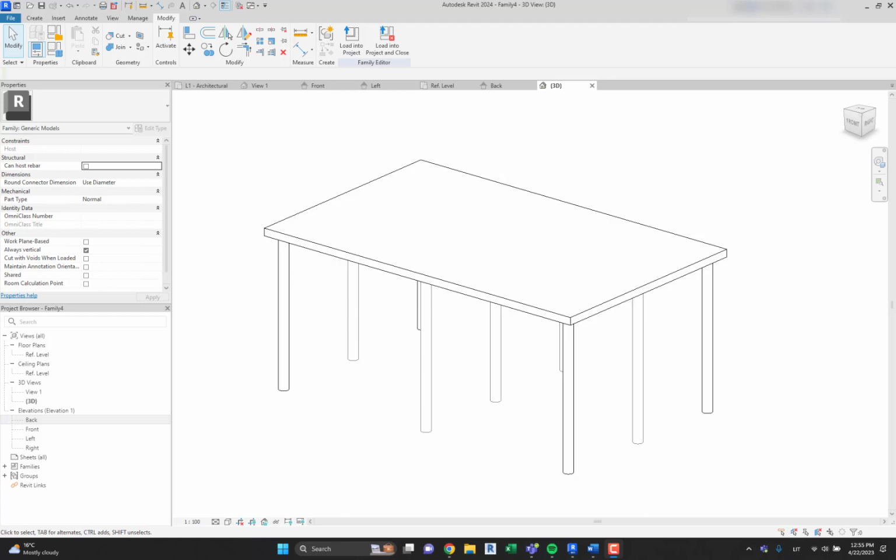Nesting in Revit allows us to place families within other families in order to display their combined geometries and make them behave like a single unit within a project. There are many use cases for nesting Revit content, such as the use of repeated components or parametric elements in an array. There are also situations where placing a set of families together would be very convenient. For example, a table and its surrounding chairs.